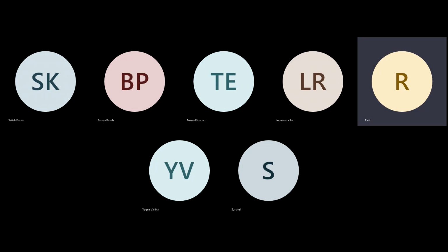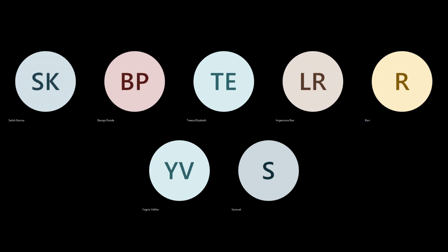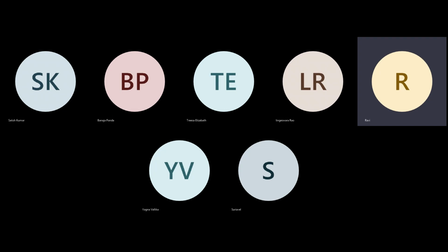So what we have to do is macro placement. When you are looking at it, you have to look at which are your modules, because you want to drive it. Otherwise, it will just go by the technique. Where is my shortest net? Where is my congestion? It doesn't care whether your module is split, because it has only 2-3 criteria: I have to meet my congestion. But there are other problems which will come later with regard to clock skew, how you have to manage your domain, etc.